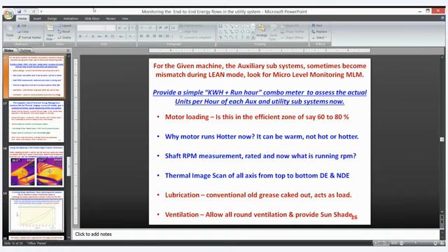Some of the motor OEMs give a 2 to 3 year guarantee; that is the refilling time as such. The grease is supposed to dissipate the temperature from the bearings to the skin, and an ordinary multi-purpose grease will not do the job for us. Ventilation also: in some of the motors, depending on the harsh environment, we can increase the ventilation fan size so that the motor end-to-end, driven and non-driven temperature difference is almost within 10 to 15 degrees.